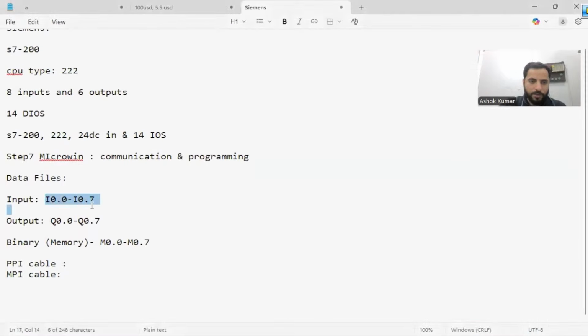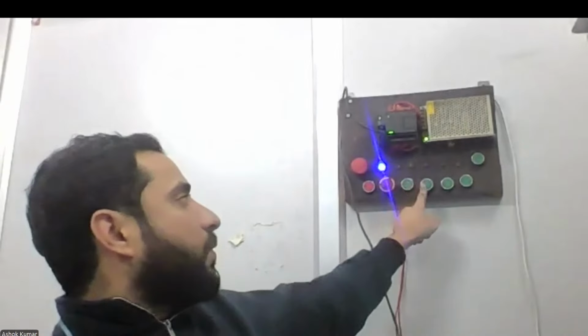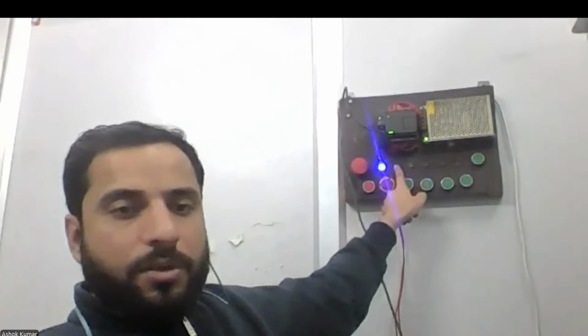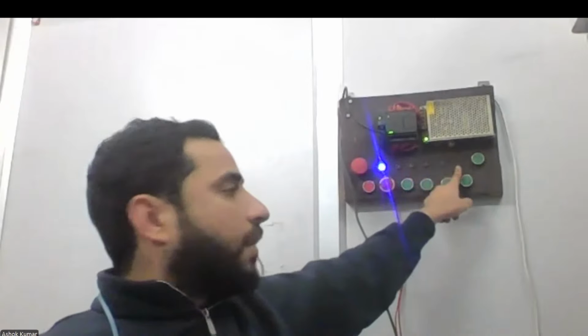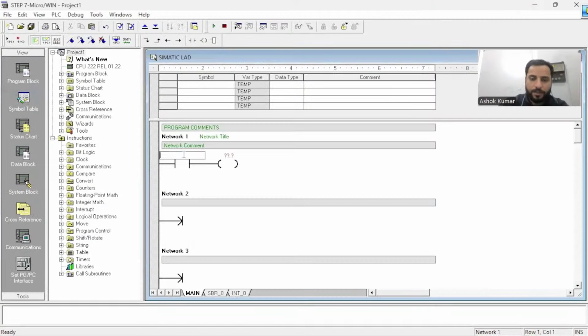Addresses are I0.0 to I0.7. We have 8 inputs. Okay. So this one is I0.0, 0.1, 0.2, 3, 4, 5, 6, 7. Outputs Q0.0, 0.1, 0.2, 3, 4, 5. Okay. Now come back, sharing my screen again. So let's take first input as I0.0 emergency and Q0.0 as first output.